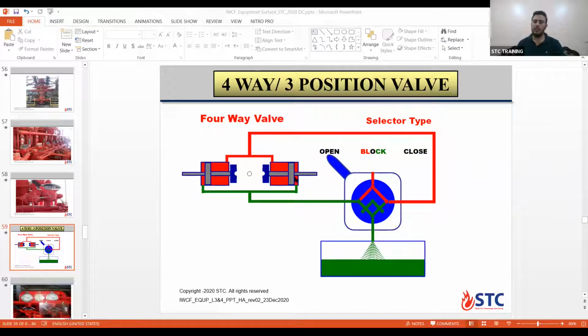So the fluid in the closing chamber is displaced to the reservoir tank. Okay, it's a closed circuit. The volume taken from the reservoir to close is the same volume that goes from the opening chamber back to the reservoir tank.